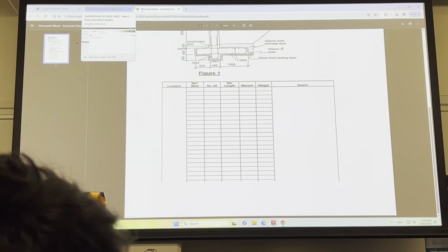sometimes they will do their own reinforcing bar schedules, in which case the consultants, all you'll put on your drawings is D16s, 16mm bar, D16s at 300 centres. Done. Your job's done. You've done the design. You're not concerned about how it fits in the concrete. That's all you do, and you move on to your next job. Obviously you're not going to get paid much.